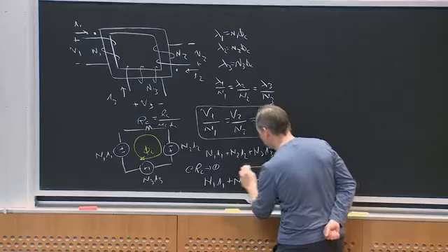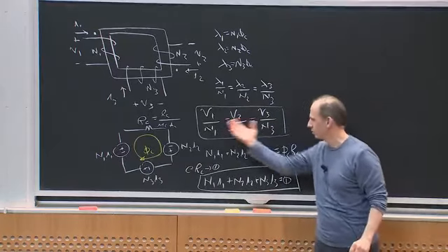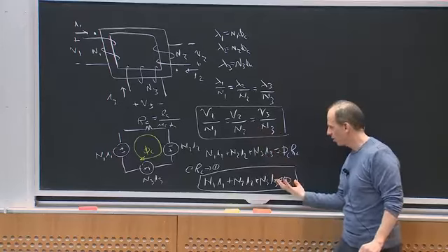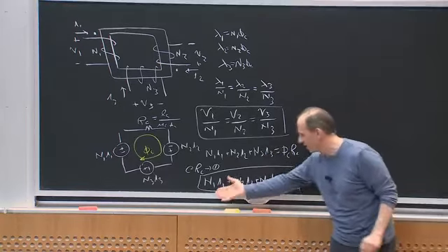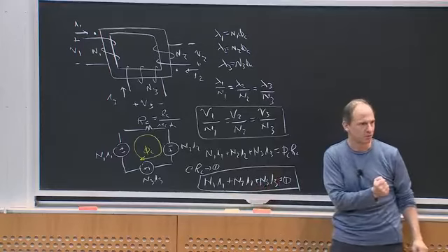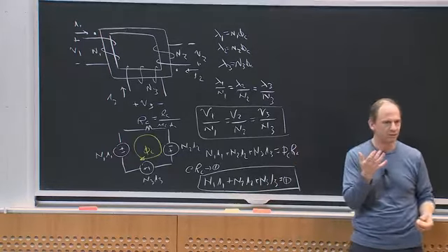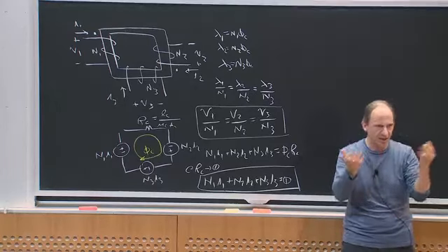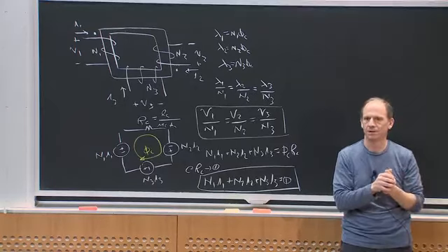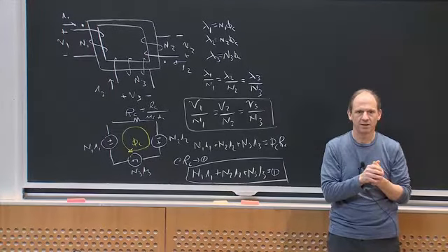So the voltage relationship just scales from 2 to 3, but the current relationship doesn't. The current relationship just says the sum of the NIs into the windings has to be 0. And what that turns out to mean is all the energy flowing in two of the ports must come out a third port instantaneously for this idealized version. Questions about that?